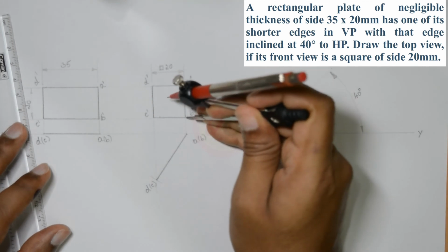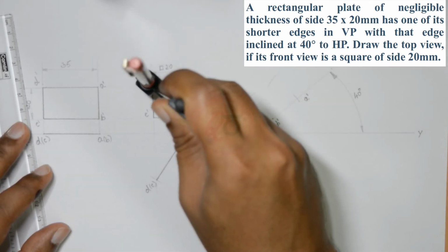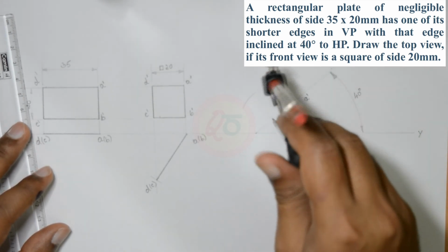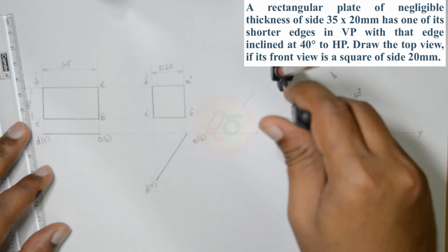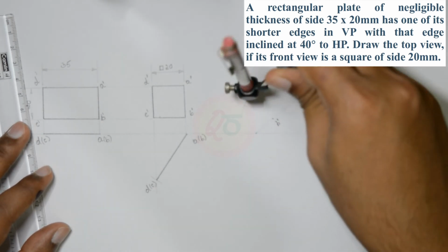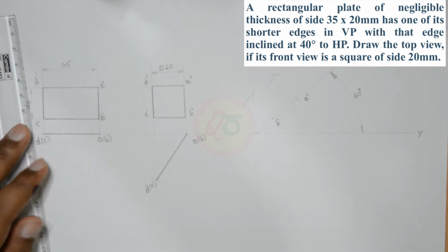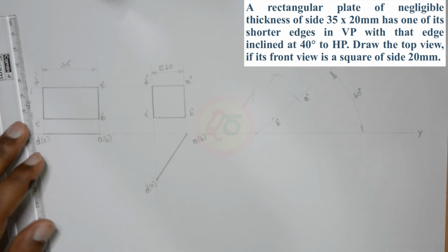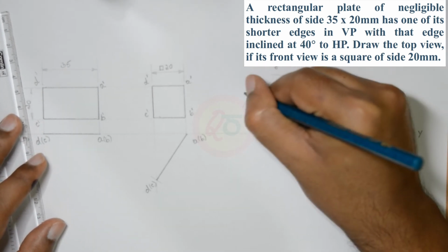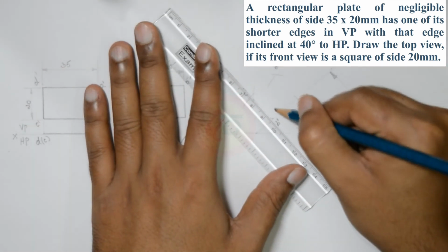Now from B dash to D dash, take the measurement from the second position front view. From B dash, cut an arc to intersect the arc from A dash. Similarly, from A dash, cut an arc to intersect the arc from B dash. Since A dash, C dash is also of the same length, this is D dash, this is C dash. Connect all the points.